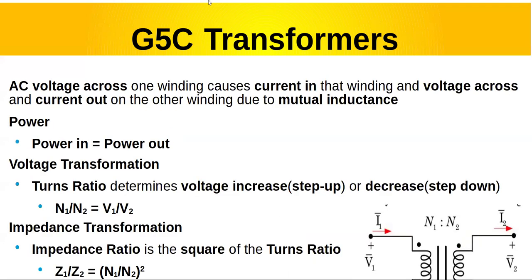And the primary and secondary are just convention. You normally input the primary and the secondary is the output, but you can certainly turn it around and apply voltage to the secondary and get your output on the primary. In fact, there's a question about that coming up.